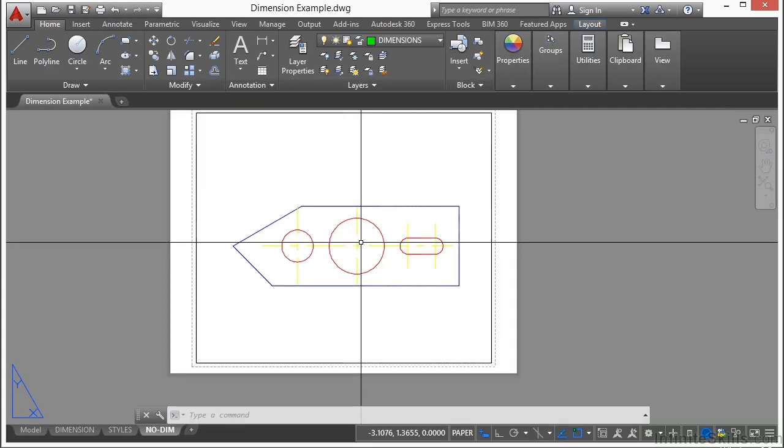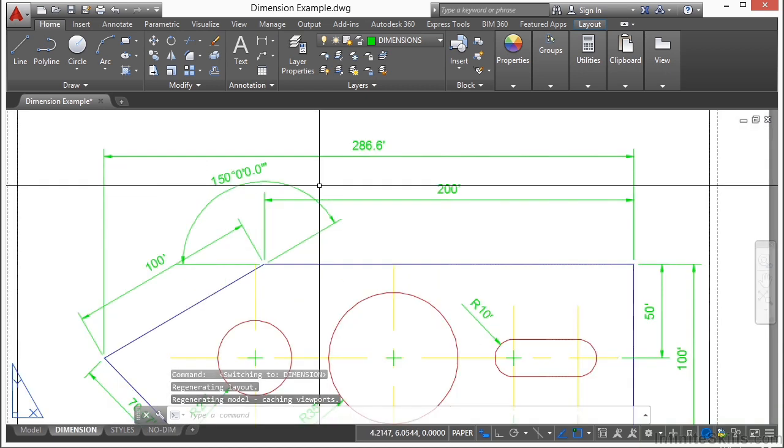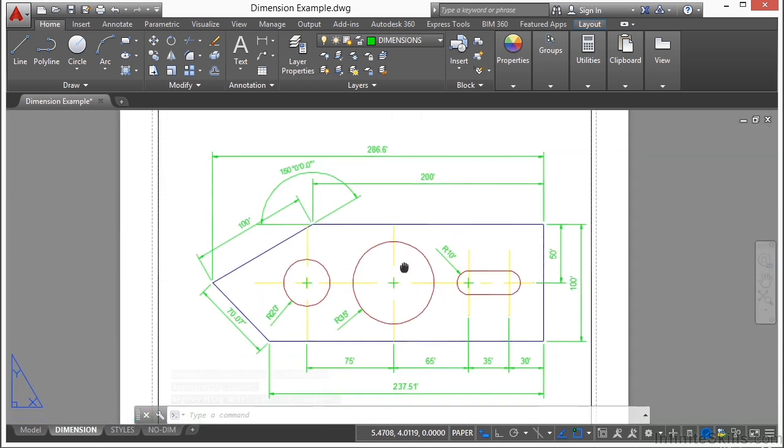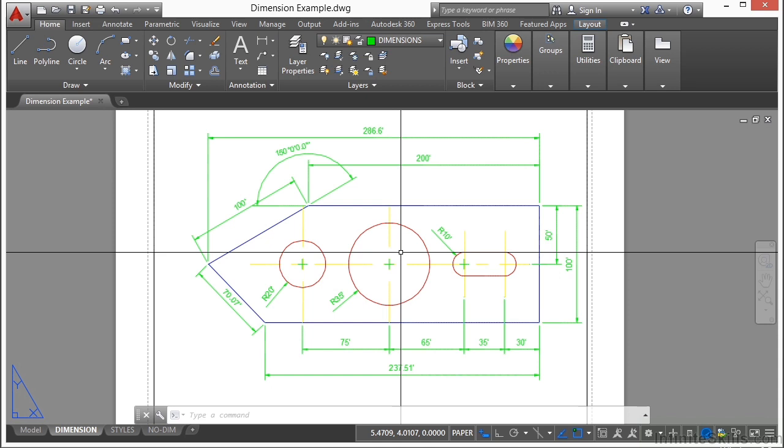You can create dimensions for a variety of object types in many orientations. Linear dimensions can be horizontal, vertical, aligned, rotated, a baseline, or a continued or chained string of dimensions. Here we have several dimensions on this bracket. Dimensions can also be associative, non-associative, or exploded. Associative dimensions adjust to changes in the geometric objects that we measure.